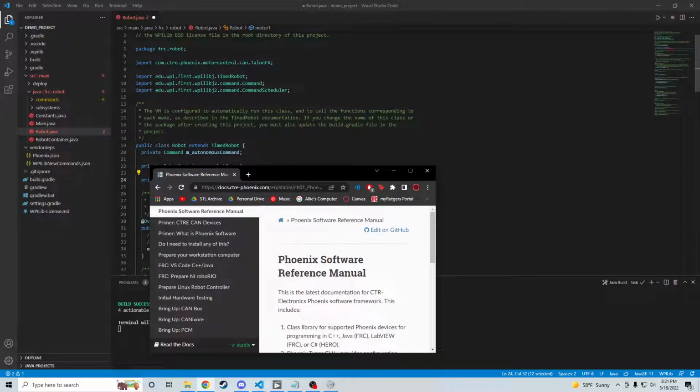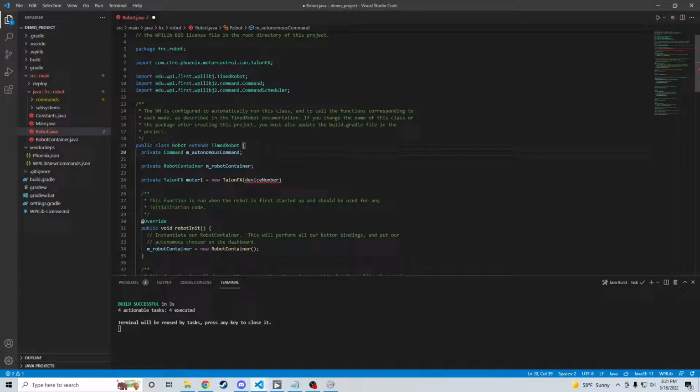And what you do is you just plug right into the robot using a USB cable, and this list will pop up of all the motors and their IDs, because each one's given a unique ID. You can press the blink button, and it'll make the lights on the motor physically flash. So you'll see which motor's motor 0, which motor's motor 1, and whatever. So let's just pretend we're going to do 0.